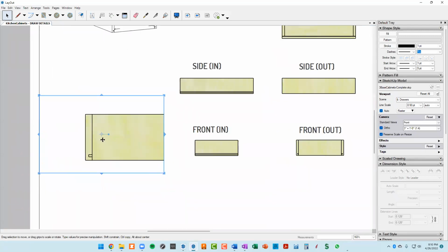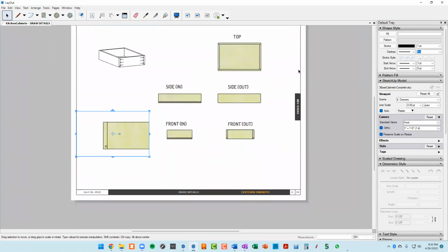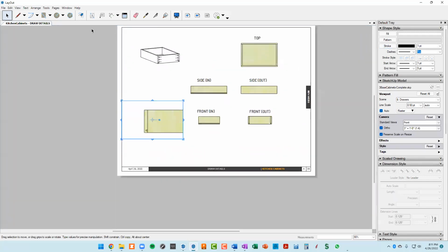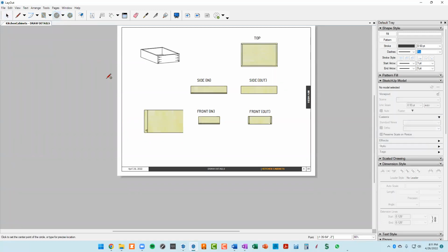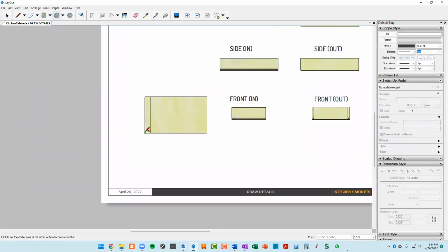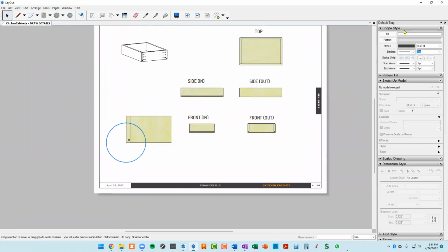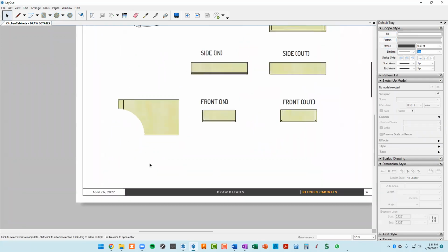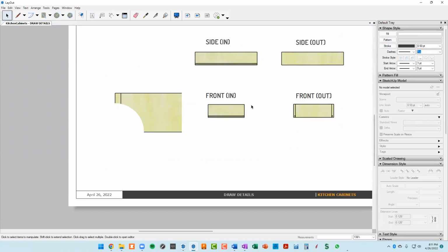But if you want to make this kind of look like that zoom bubble that I showed initially, what you would do is you can just go to any of these drawing objects. So I'm going to go to circle and I'm going to start right here and draw a circle like that. Okay, so now the circle is just like any other drawing object in Layout. I can go to my shape style and I can do a fill. Okay, I can do a stroke. Stroke is going to be what's around the outside of it.